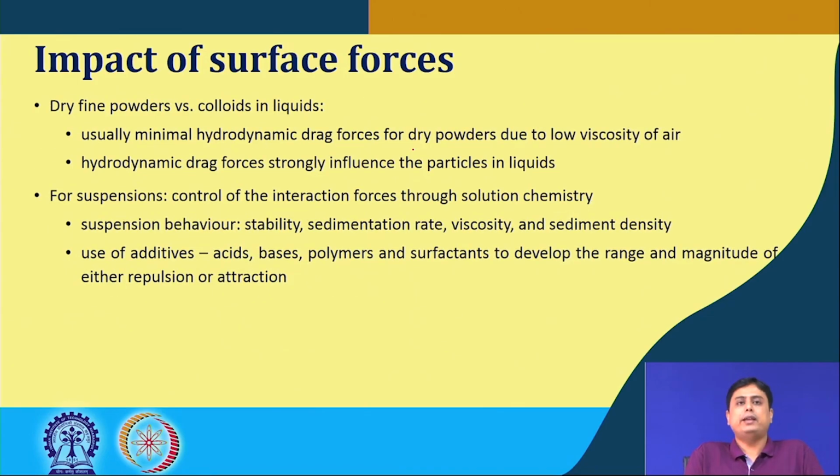Now, the difference between fine powder and colloids in liquid is that in dry fine powder exposed to air or some other gases, there is very minimal hydrodynamic drag force due to the very low viscosity of the air. But in the case of liquid, the hydrodynamic drag force is the dominant mechanism, as we have seen in our earlier classes, so it influences the particle in the liquid.